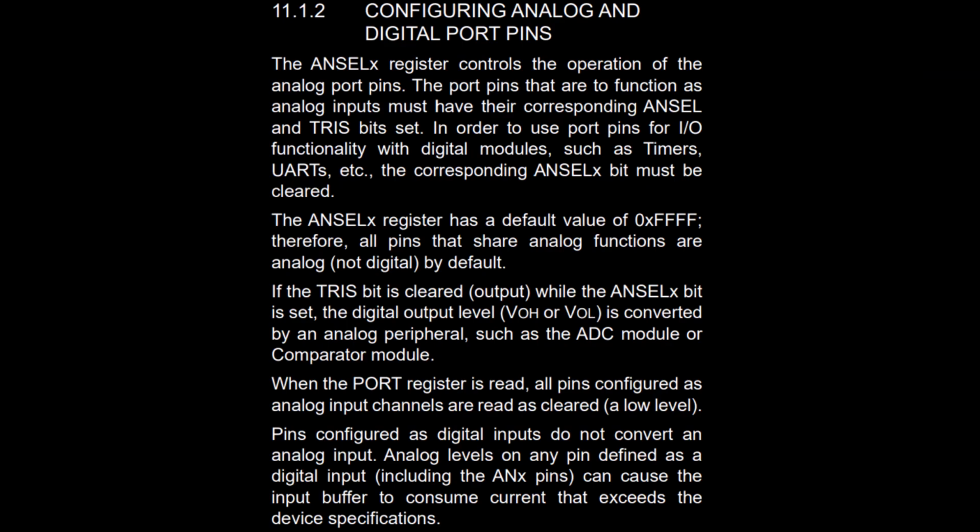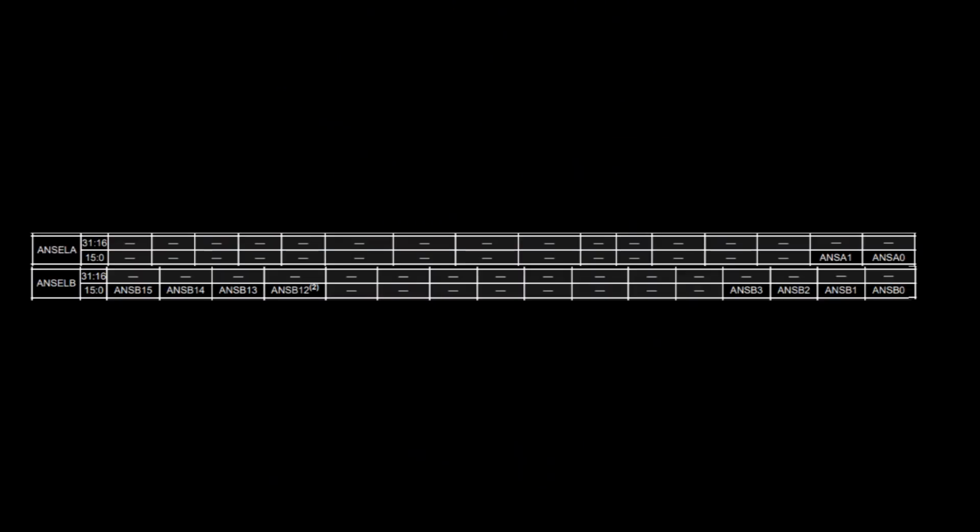The next step is to configure the terminals to be used as digital, regardless of whether they are inputs or outputs. In the microcontroller datasheets, it is indicated that the terminals by default are configured as inputs and of analog type. The registers that control this configuration, for each port, are called ANSEL. For port A, it would be ANSELA, for port B, it would be ANSELB, etc. To configure a terminal as digital, the bit of the aforementioned register must be at logical 0. Bit 3 of port A doesn't have a bit associated with the ANSEL register, so it is already digital by default.